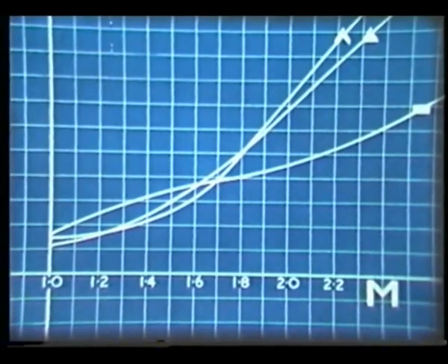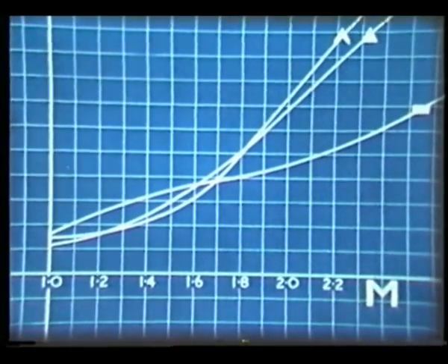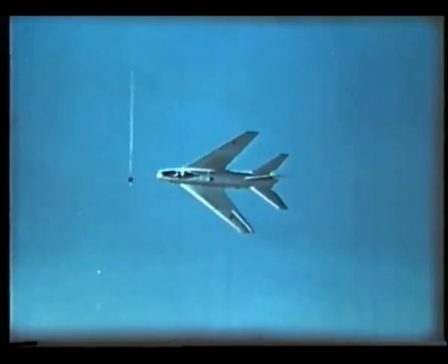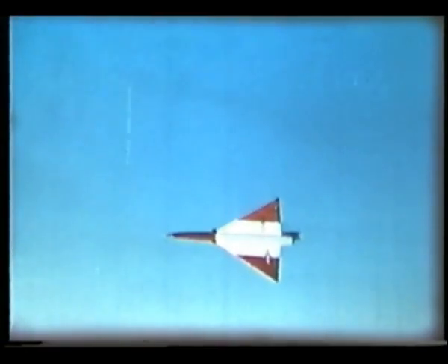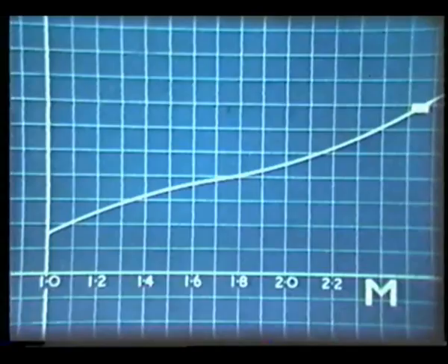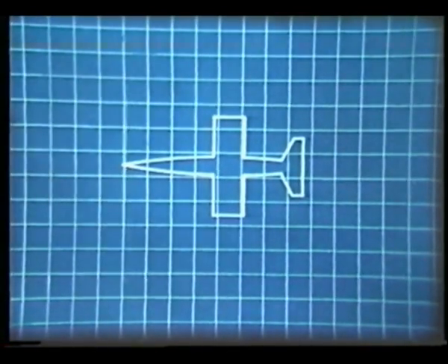It looks as if below about Mach 2, the advantage for low drag lies with the swept shape. Or with the delta. While above Mach 2, the straight wing planform seems at first sight to be better. But drag can be reduced still further above Mach 2 by increasing sweep still more, provided the low-speed problems can somehow be overcome.